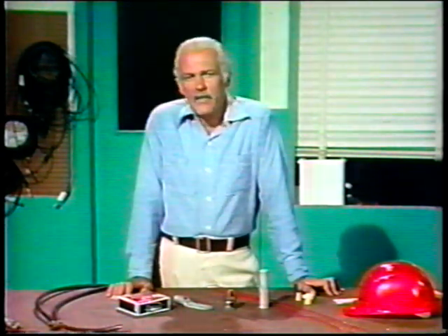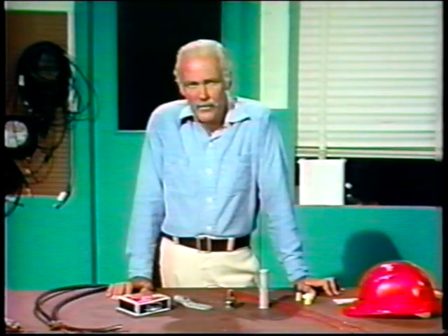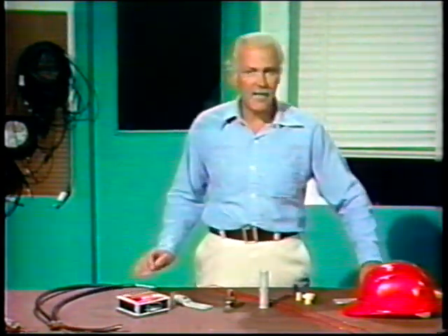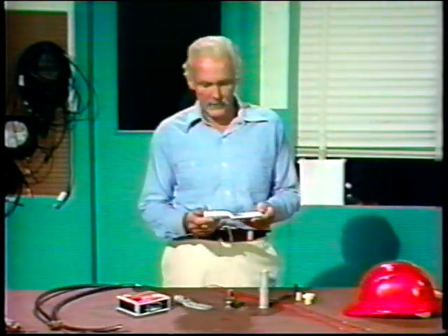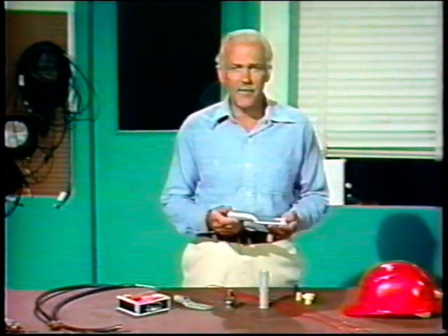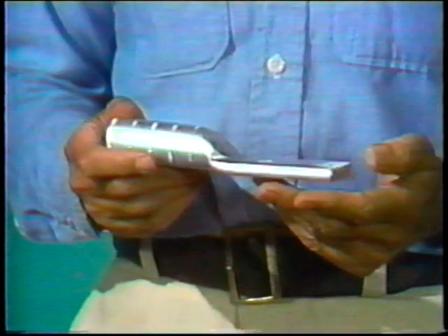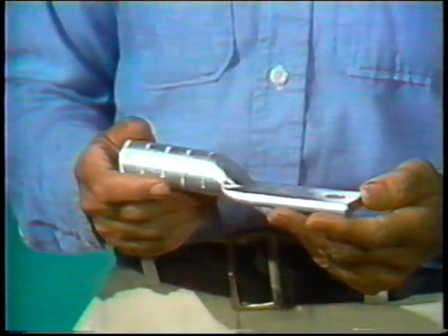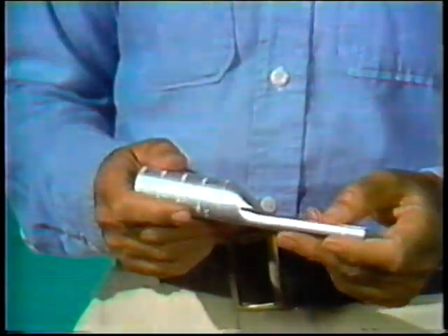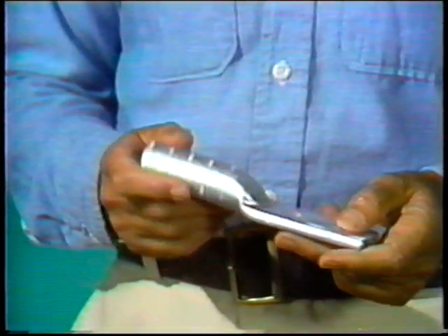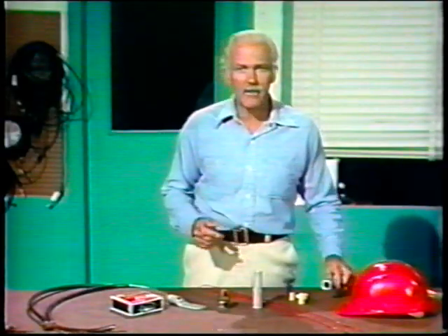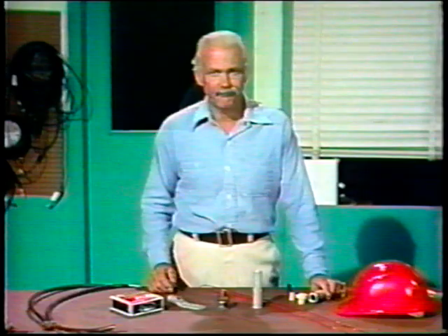However, some thermal connections do require special hardware that are used with solder to connect the ends of the conductors. Now, here's an example of a thermal lug. If you're familiar with lugs, you might expect to see a hole somewhere on the barrel of the lug. But on a thermal lug, a hole would allow solder to drip out of the barrel as it was applied. So one way to distinguish between a thermal lug and a mechanical lug is that you won't see a hole on the barrel of the thermal lug. Otherwise, the general construction may well be identical.